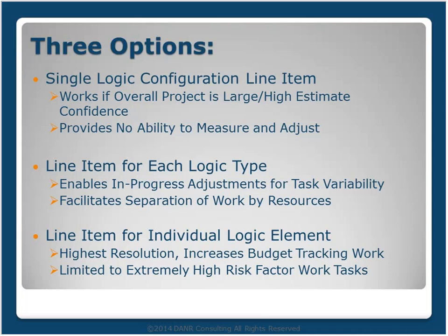And so I would just suggest that you tend to shy away from too much detail because it can be as dangerous as not enough detail. Just as an example, if you're looking at converting 200 old Provox FSTs to Delta V, and you know that the old Provox FSTs aren't documented very well, the logic narratives aren't correct, that type of thing, then you might want to really hone in on those specific activities and make sure that you're tracking them at a pretty granular level.